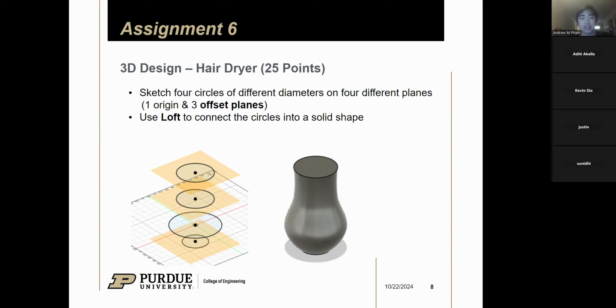But there are many cases where you might be tempted to create extra planes that you want to build off of, right? Sometimes you might have two faces and you want to create a feature that's in the center of them. Or you might want to have another feature that's offset or tangent to something else. To create that, sometimes you might need to use a plane. So we're going to teach you how to use planes today, and show you some of the cool things that it can do.